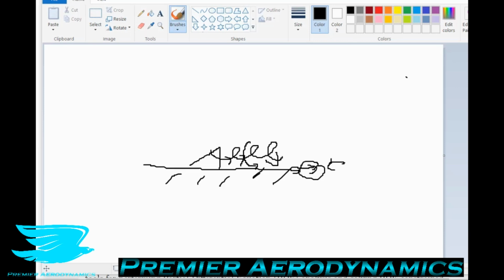And the reason why they don't have the drag penalty is because the vortices that they produce are pretty much always contained inside the boundary layer. And the boundary layer is already slow moving anyway, so the pressure drag deficit that you get from a regular vortex generator is not incurred with a micro vortex generator.